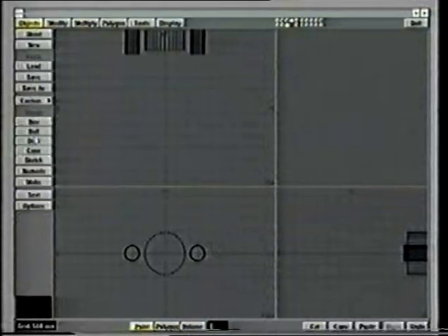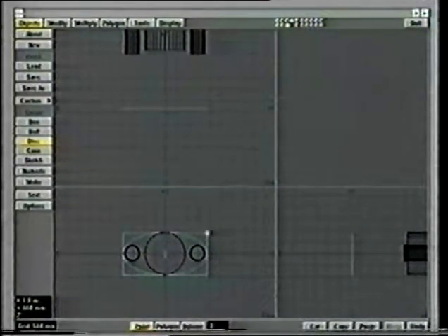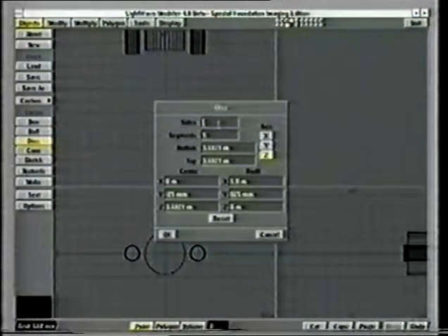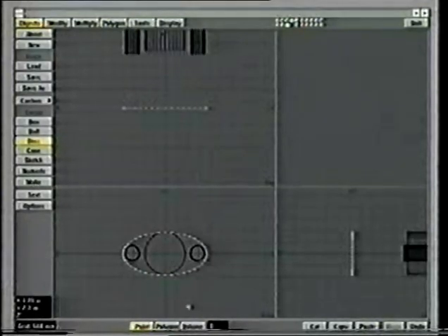And let's try a disc that will surround the whole thing. Try and get it as tight as I can around the shape. That looks pretty good. Check the numeric requester, and around this we're probably going to need about 40 subdivisions. Okay, make. Alright, now what I can do is select the polygon that I've created there, and I can just remove some of the points.